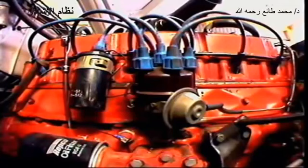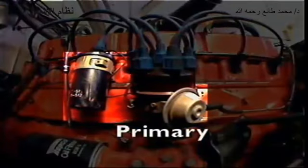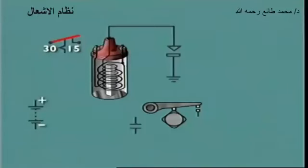When these components are connected together, they form two distinct circuits, primary and secondary. In the primary circuit, the positive terminal of the battery is connected to the ignition switch, then to the positive terminal of the ignition coil. A connection is then made from the negative terminal to the contact breaker moving contact point.